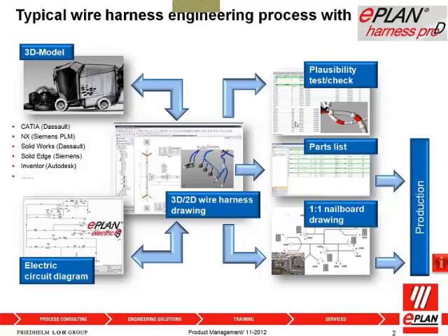Things like your bend radiuses are taken into effect. You can also identify any collisions with your routing paths. Also, for any connectors that have a certain size socket, if you're trying to fit a wire that may be too large for that socket, the software will automatically take that into account. There are also some calculations taken into account, as far as the overall size of your harness. The length of your harness and the length of the wires being connected to the devices will automatically be calculated as well.